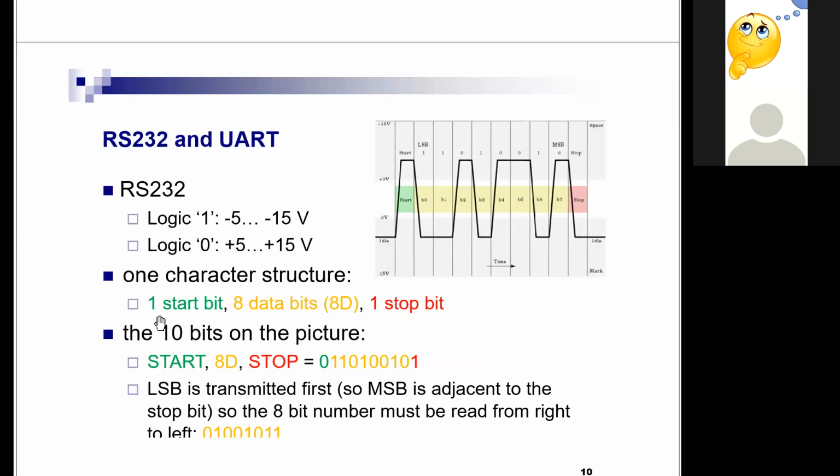Okay, so I told you there will be a start bit, a stop bit, and the data bits. You all know the start bit is denoted by 0 and the stop bit is denoted by 1. And here how many bits are there? 8 bits are there. So now you tell me, is it odd parity or even parity? See the data bits and tell me, odd parity or even parity? Students, tell me whether it is odd parity or even parity. Odd, ma'am.